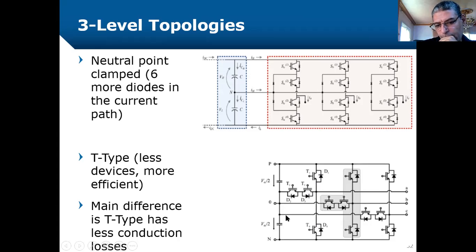And for the lower part, if this transistor is turned on, the diode will allow current flow if switch T4 is turned on simultaneously. So T2 with T4 is forbidden to conduct together, because it will result in a short path for the lower DC link half.